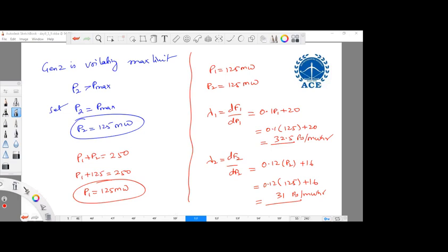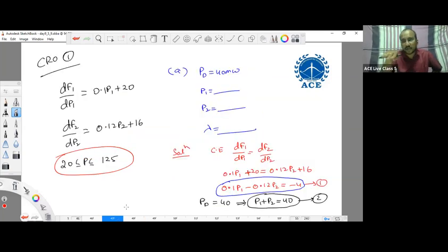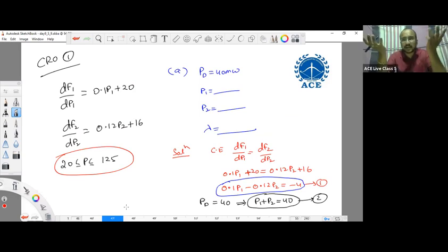Sir, in hot power, as you said, for the second one we are making one section hot. But what is the use of that, sir? Because it's not delivering any power now. It is just floating on the bus bar. Because load is not constant. Whenever the load changes, we will load that alternator to meet that requirement. Whenever the load changes, we should generate the power based on the load condition. Generation and load should be balanced.